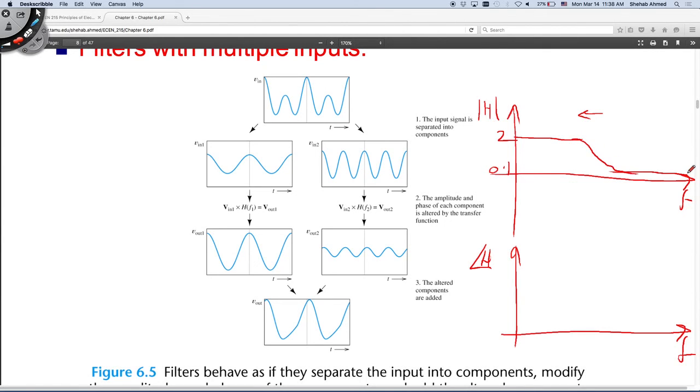And between them, it's doing something. It's going to go from here to here, right? It can go between them this way, or it can go between them this way, or this way, many ways. Do we agree? And the way it goes between them will depend on how I design the circuit inside this box. But the asymptotes are what we will typically use, because as an engineer, I want back-of-the-envelope type calculation. The asymptote at low frequency will be like this. The asymptote at high frequency will go this way. So this is what happened on the magnitude plot.